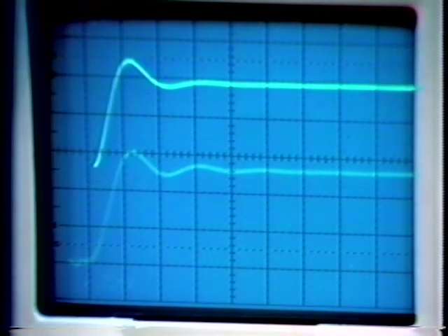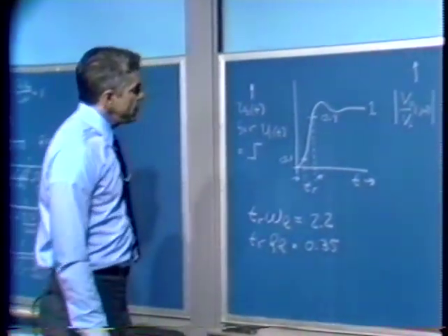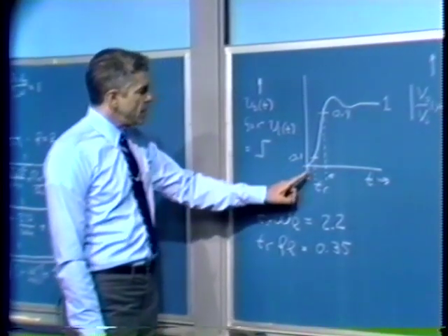So we've shown, at least in this one particular case, that we can get very good approximations to the behavior of a complicated feedback system as either a first or a second-order system. And what that allows us to do is, for example, translate between transient responses which we might measure and frequency responses which we might like to know as an aid to the design process, by really taking advantage of properties of first and second order systems. There's a fair amount of this sort of material in the book, and the translation has to do with parameters measured in the time domain.